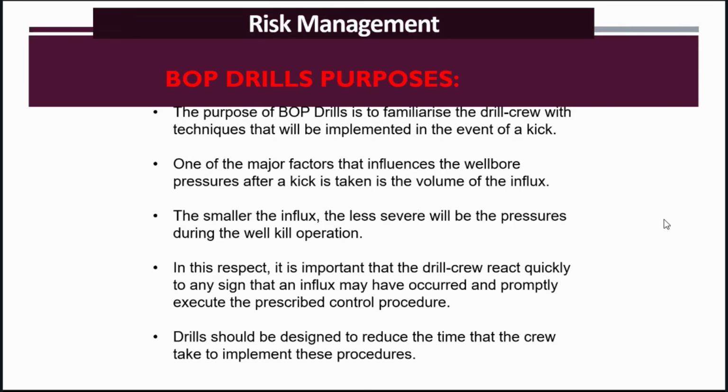Then companies are doing drills. Drills means, in the event of a kick, how to close the BOP. It is called a BOP drill. A kick is not actually occurring, but they are practicing how to open and close the BOP, so that when an actual kick comes and they have to open and close the BOP and secure the well, they are sure of the procedure to follow, and they should not panic.